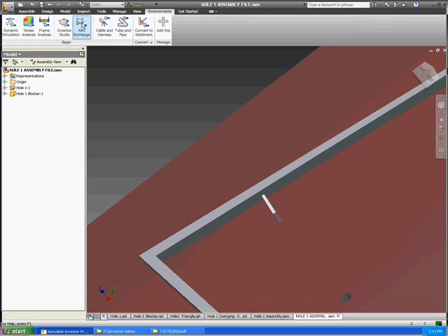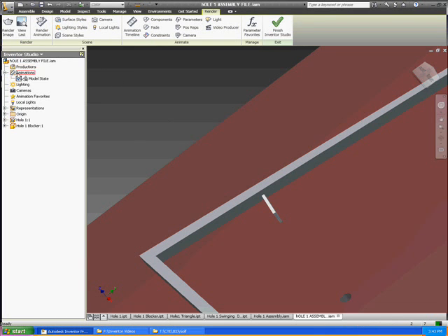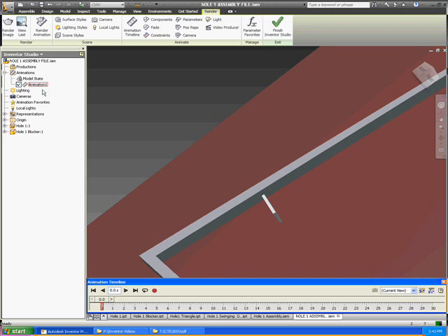And now I switch to the environment called Inventor Studio. So click Environments and then Inventor Studio. From here, you create a new animation by using the browser. I right click Animation, select New Animation, and it comes up in the browser as Animation 1. Double click the animation to activate it. That turns on this animation and means that the parts that I animate will then be active and move.